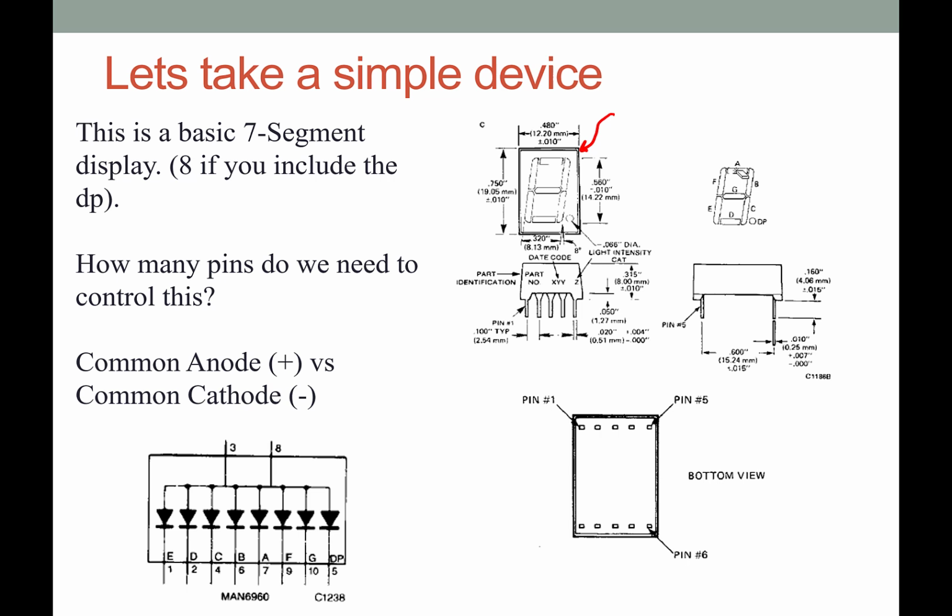And so how is this being controlled? Well, in this case, what you see is 2 ports, or 2 pins, are controlling what we often call the anode of the diodes, and notice that all of the anodes in this one are connected together.